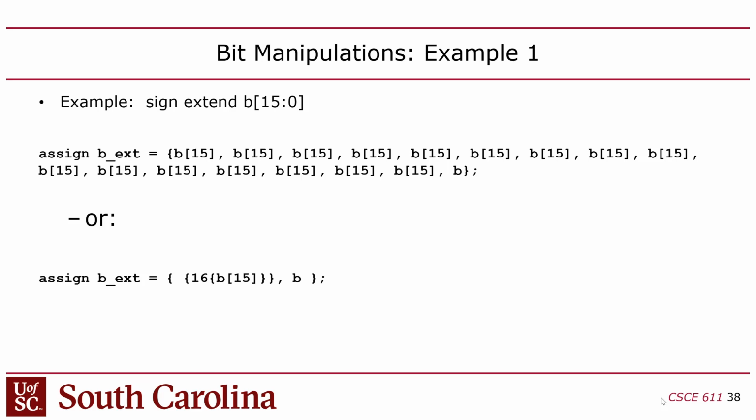Oh yes, here's why I put this in here: you'll have to do this in the RISC processor. Sign extending, you learned about that in 2.12, right? Sign extending is when you convert one width to a wider width. You take a signal that's 16 bits, for example, and you put it into a memory location that has 32 bits, or into an input on an ALU that has 32 bits, right? Kind of a type conversion, right?